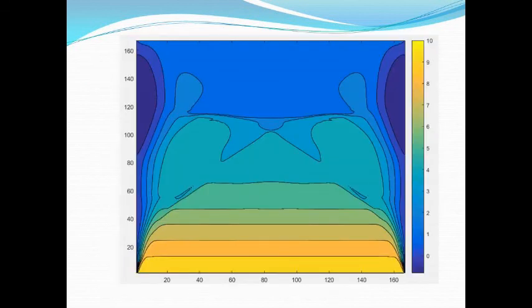This is a contour plot of u velocity with the source, or u1, at the bottom of the screen and the channel mouth, or u end, at the top. Also taken at time step 10,000, the velocity clearly drops off quickly in the region where the height increases suddenly at about x equals 50.